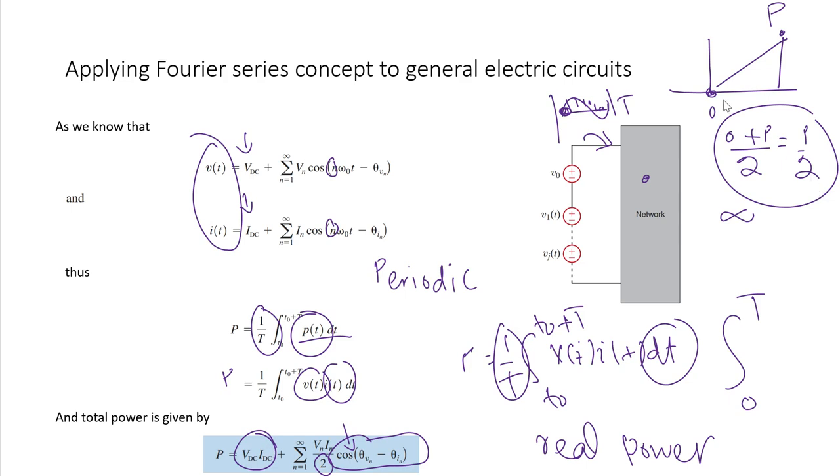And after that, since these powers are changing, we conclude that all these powers are dissipated as AC powers. So AC power is Vn In by 2 multiplied by the cos theta of voltage minus current. So voltage minus current will give us this angle of cos theta, the power factor. So this is the angle between V and I. This is pretty much it. You just have to remember that we are multiplying by cos theta and we are using Vn In by 2. That's it. It's not that complicated.